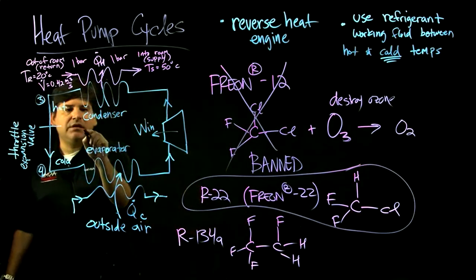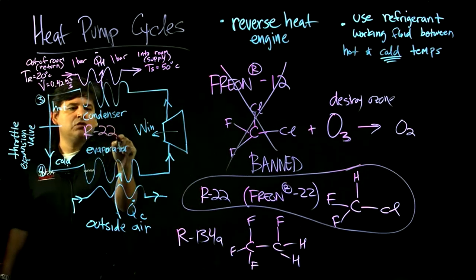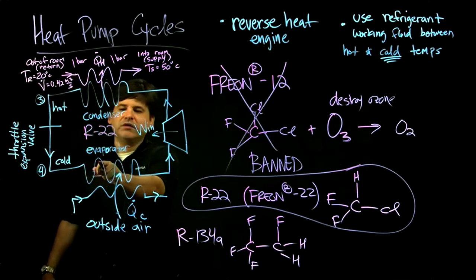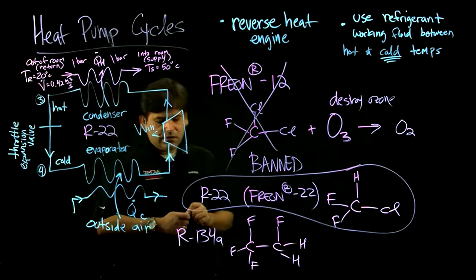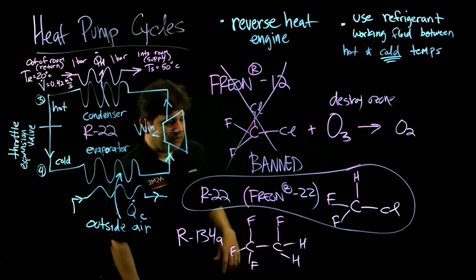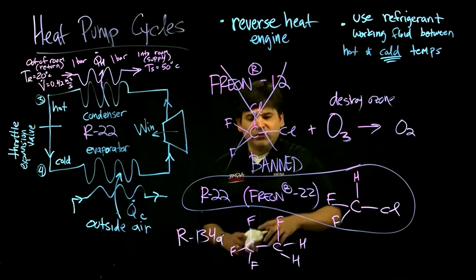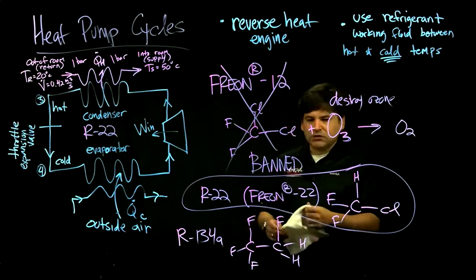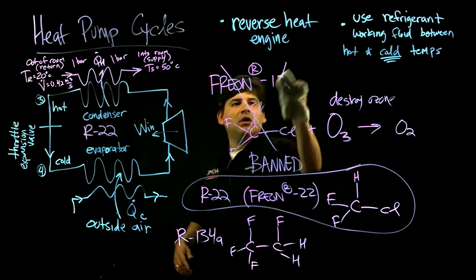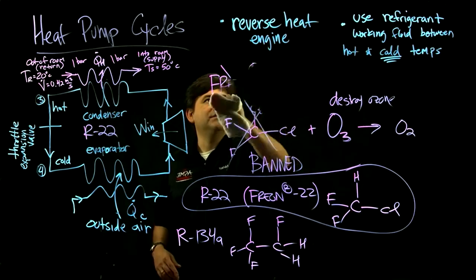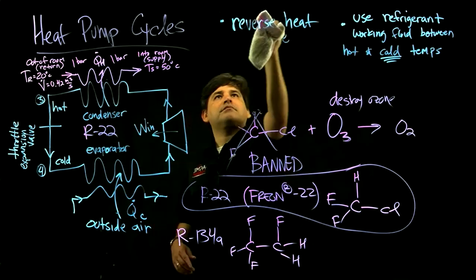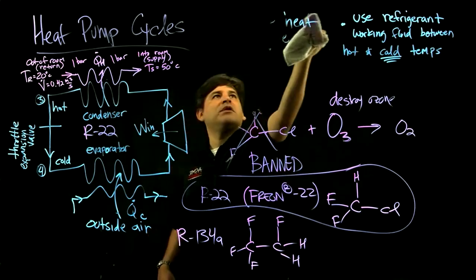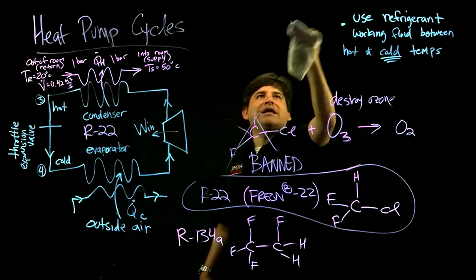So this is going to be an R22 working fluid cycled through the evaporation, the throttling valve, and this particular heat pump cycle, this reverse heat engine. This refrigerant is going to get throttled to go to low temperatures when it expands. So we put the numbers on the heating application.